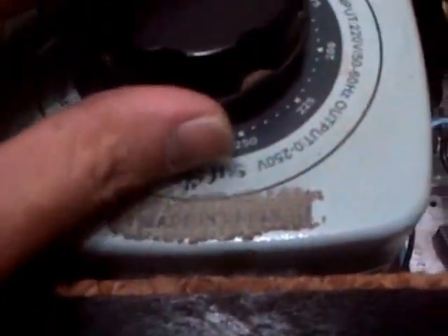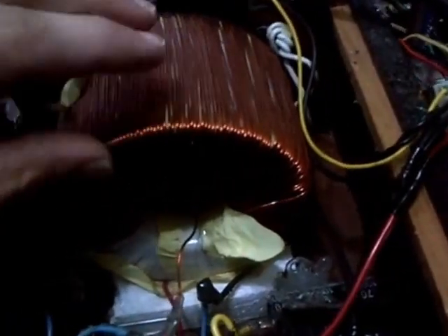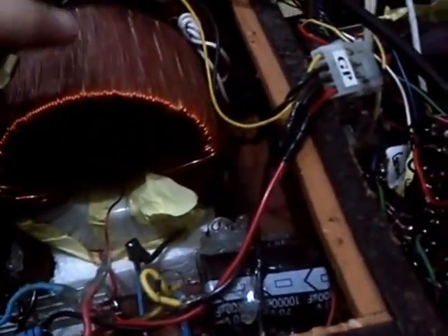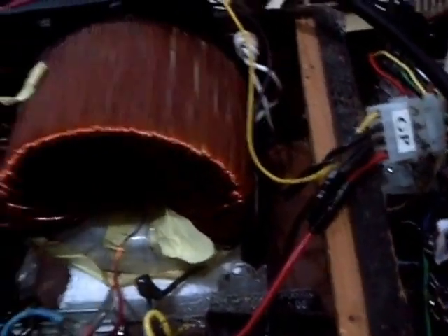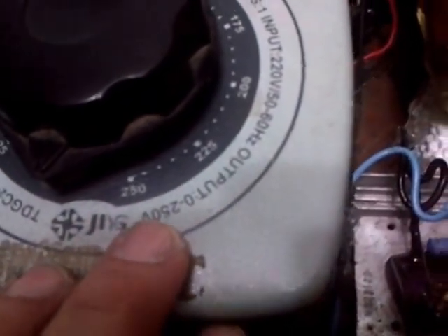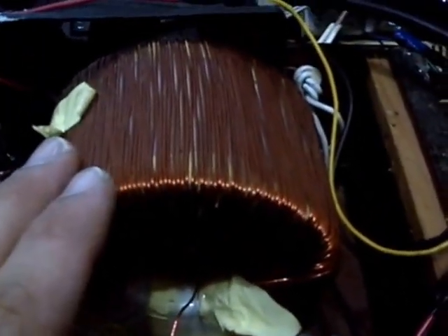My power supply has this variac that is fed with 250 volts. Okay, it has the indicator for the voltage and for the amps, and here I used a similar variac. I opened one like this and wound 18 gauge wire. There's maybe 100 turns or maybe more. I don't remember now. So here I get from 0 to 250 volts, actually a little bit more, but 250. And here I get from 250 to 100 volts, step down.